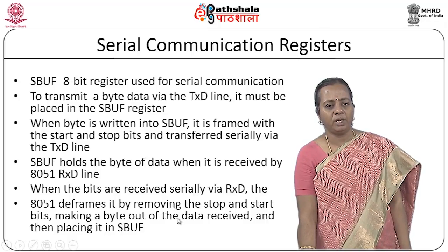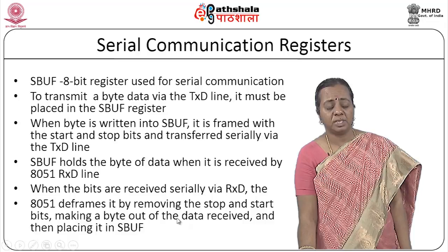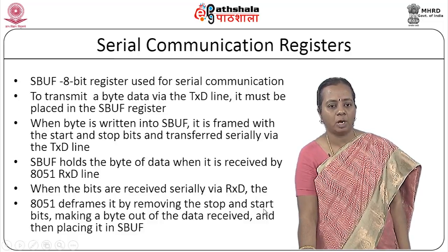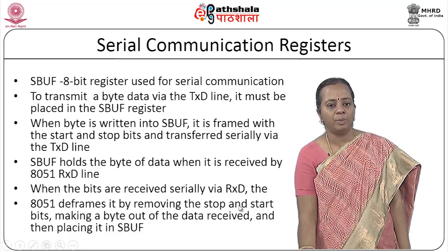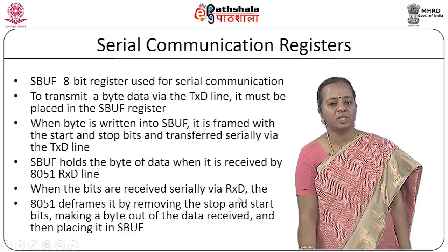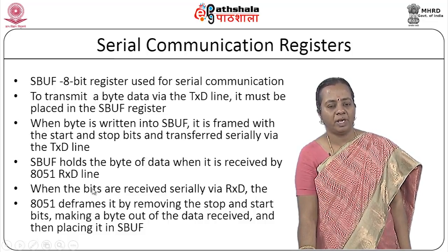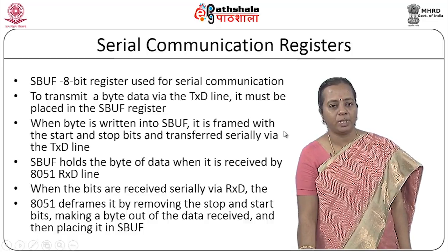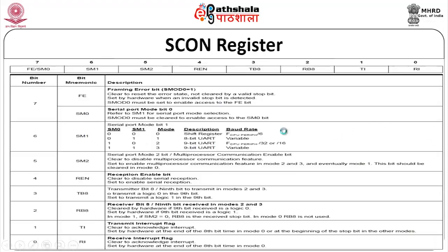The second problem here is that when I am receiving data, it will have a start bit and a stop bit, as in the UART standard, which say that the data bits are coming in between. These two things have to be removed before giving the word to the system, whereas while sending, they have to be attached. This process also has to be done at SBUF only.